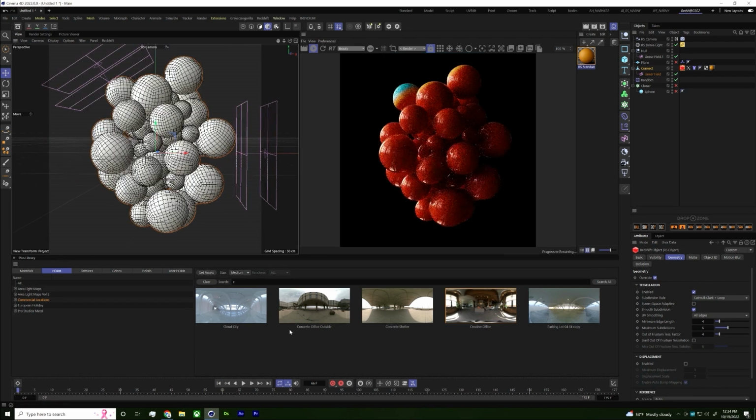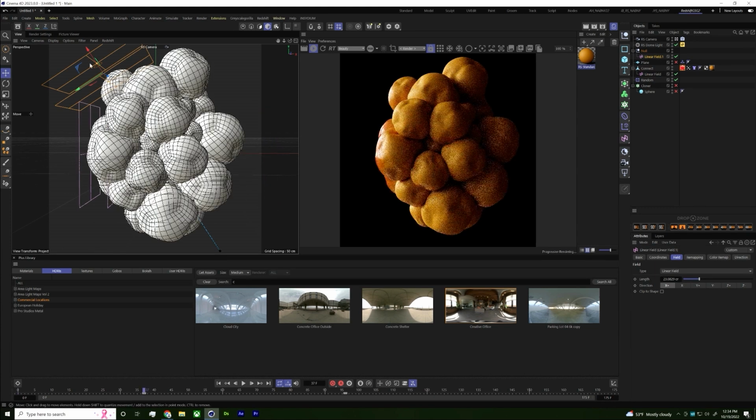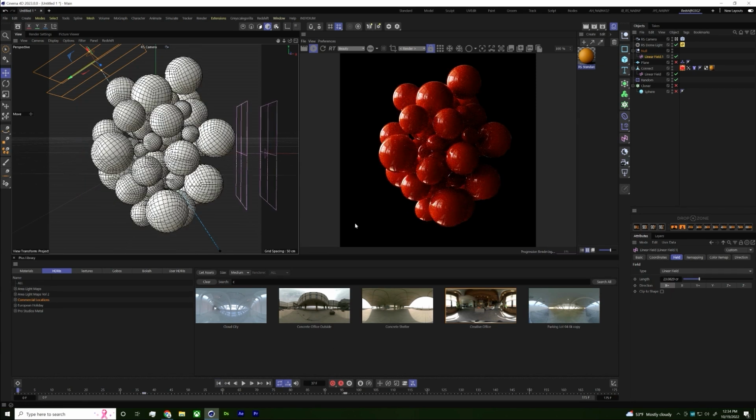Okay, so we are at this point where we do have to tweak our final keyframe here on this animation. And so that's something we could do right now by going to our second linear field and finding our first keyframe, moving that linear keyframe up till it's not visible anymore, and now we could just reset that keyframe, and that should work fine. Okay, so let's run through it and see where we are.